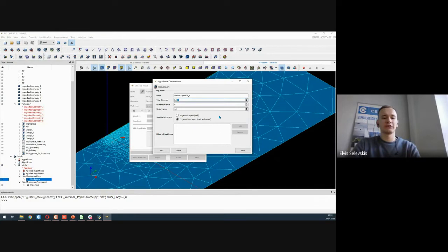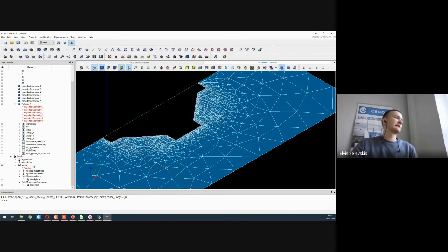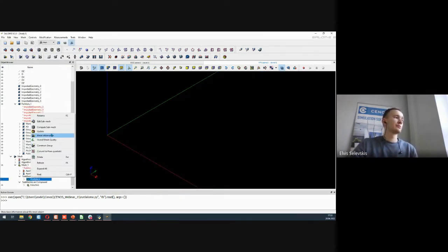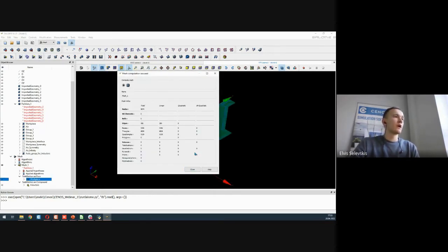It's probably okay if you run it with 0.004 or 45, but still, it's best to consult with that calculator what kind of value, at least roughly, to input. You can press OK, apply and close. Once again, clear the mesh data and recompute the workpiece so that we can see how the viscous layers actually look like. Yeah, so here mesh computation has succeeded.